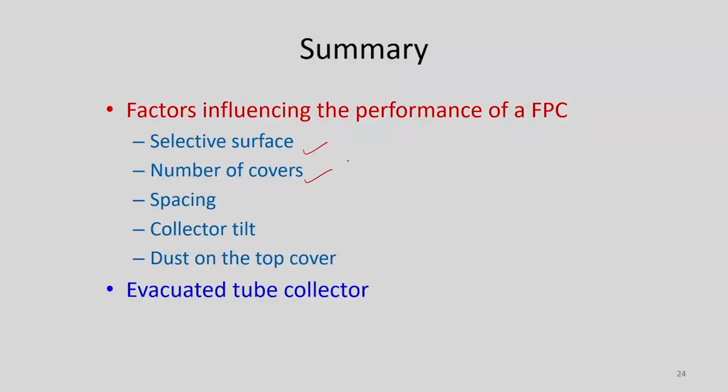Also, we have seen the effect of the number of covers with selective surfaces and without selective surfaces. Also, we have studied the influence of spacing between the covers, and the role of collector tilt and dust on the top cover. Finally, we have understood how this evacuated tube collector works and what is the need for development of this kind of technology, of course, for increasing the conversion efficiency by reducing the cost.